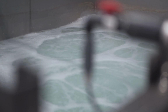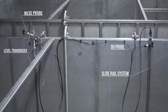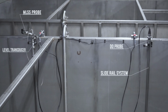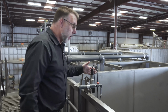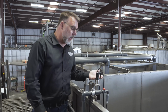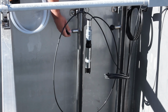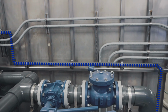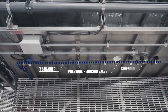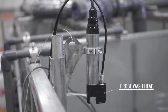Aeration chamber 2 has all of our sensory equipment. In this chamber, we are monitoring level, dissolved oxygen, and mixed liquor suspended solids. All of our sensory equipment is installed on Cloacina's slide rails. This allows the operator to raise the unit and inspect or perform maintenance without removing it from the chamber. All sensory equipment is also connected to the automated wash system. A common solenoid valve will open and supply water to integrated spray heads for each component.